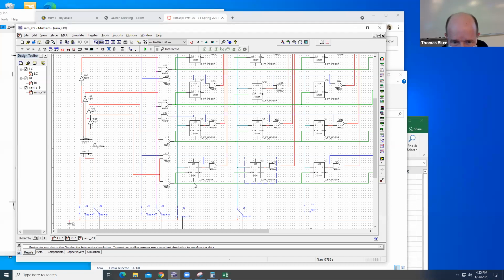The W is connected to the clocks. Remember that with these flip-flops, you have to go through a positive edge. So this W is going to control when you write. And over here, A and B, they go to the decoder. The decoder is our addressing system from way back in lab 4. So this determines where you're writing, which of the registers you write to. These determine the data that you're writing, and W determines sort of if and when you write.